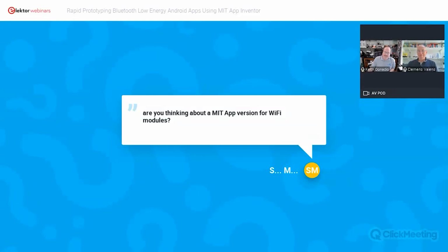So it's funny you should say that. Microchip, as some of you may be aware, has a lot of modules, and Wi-Fi modules are one of those. We have the WINC1500, which is our most popular Wi-Fi module. It's a simple SPI interface to your host microcontroller. We actually do have small evaluation boards very similar to the AVR-BLE board.